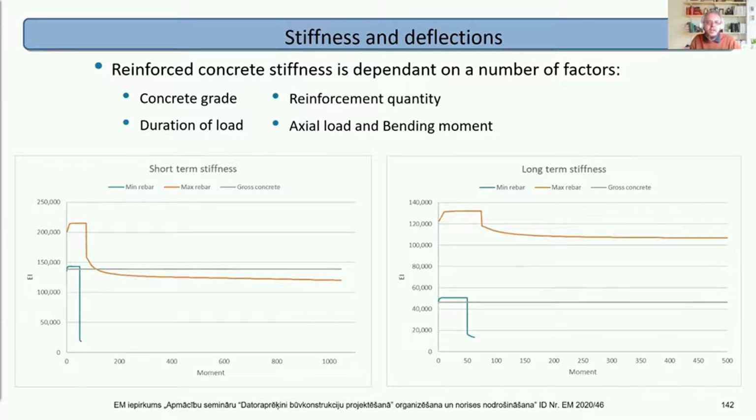You can then use that to give you the reinforcement, but the deflection might be based on your gross concrete section, for which you can get an initial approximation based on the Young's modulus and creep factor.